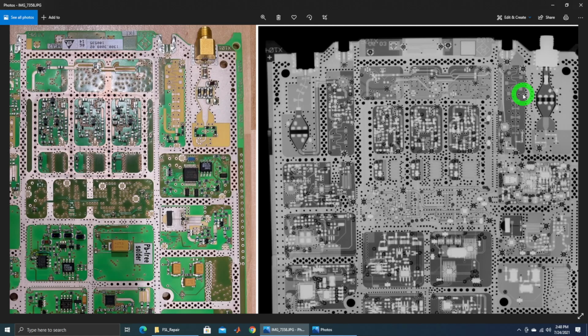Remember, these are superheterodyne, as I said. They up-convert and down-convert, and if you have frequencies that are present where they shouldn't be, even if you're not interested in them, they will overlap with the IFs and it will cause a whole bunch of problems. You can see a whole bunch of LO filtering over here. These are the different LO bands so that you can have a single pure tone coming in from the synthesizer. It's quite compact actually, very difficult to follow even with an X-ray.